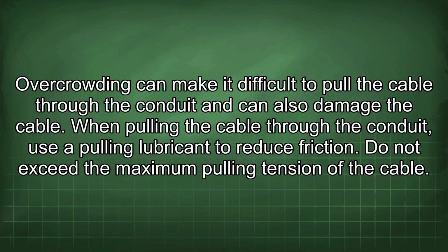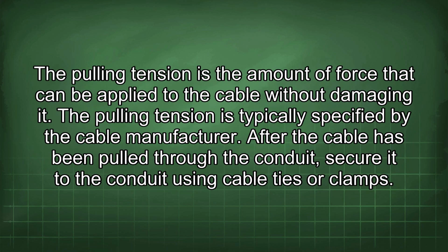When pulling the cable through the conduit, use a pulling lubricant to reduce friction. Do not exceed the maximum pulling tension of the cable. The pulling tension is the amount of force that can be applied to the cable without damaging it. The pulling tension is typically specified by the cable manufacturer.